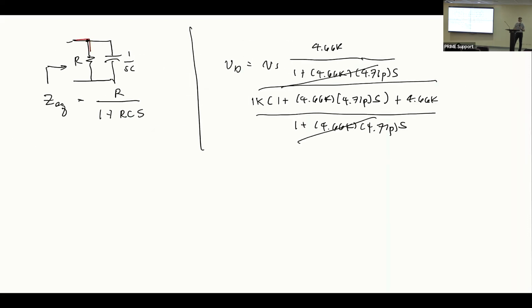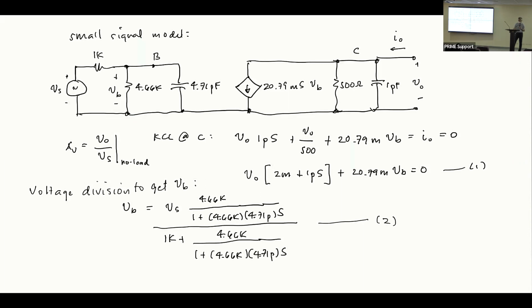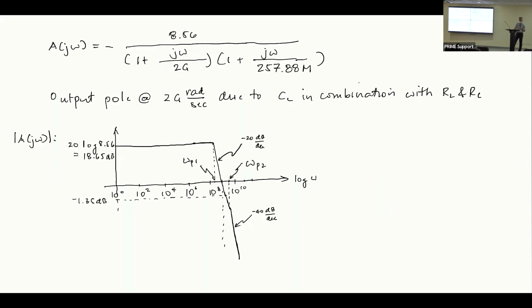Okay. Note, no? What is the resistance that is seen by my 1 picofarad? That is 500 ohms, no? 500 ohms. If I get RC, okay, and then I get the reciprocal of that, ang lalabas that's equal to 2G. Okay, that will be equal to 2G.